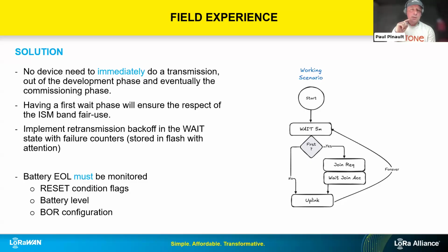In the past, the DevNonce was random. So you get a random number, and the LNS has to basically store all the DevNonces. And that was a problem in security because, in fact, the LNS did not store all the DevNonces. So basically, there is a risk of replaying a join request with a previously used DevNonce.